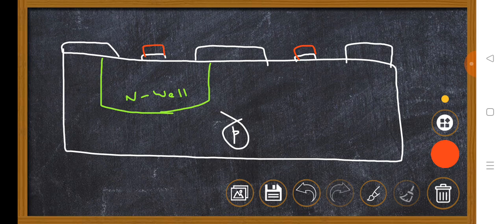Absolutely, diffusion is the next step. Don't forget, in the diffusion, what is the important step we have to talk about? Absolutely, heating the substrate to a high temperature. This substrate we have to heat, and this substrate we have to heat to the high temperature. Is it clear? After heating the substrates to high temperature, what should we do, guys? We have to expose impurities. What type of impurities are required here, since it is an N well? Absolutely, which type of diffusion do you require here? You require p diffusions here, right? Is it clear? You require p diffusions here. Here, which type of diffusion do you require? N diffusion. Absolutely, you require N diffusions. I hope you are clear.